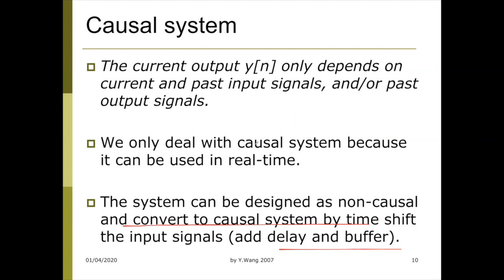Think about if you're going to design your system. You say, okay, I'm going to remove this noise using this filter, but I need to look at like 2 seconds of samples, 2 seconds of audio. Then you can think, maybe we can convert that to sort of real time, but I at least need to buffer 2 seconds because my filter relies on 2 seconds of audio. So then you can think about whether that's realistic.